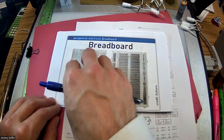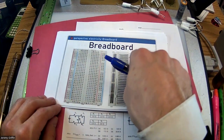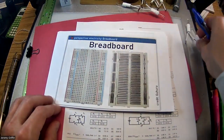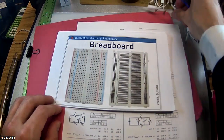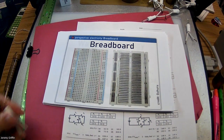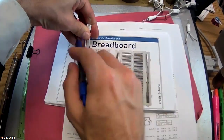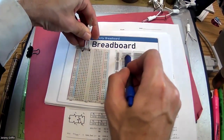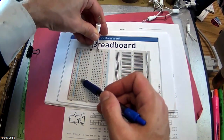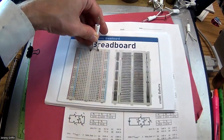So if you know what's going on in the back, just look at the front, because the front just looks like a bunch of holes. But if you know what's going on behind the scenes, you can know how to wire things up. What I would not want to do with a single resistor is plug it in something like here and here. That would be completely pointless because there would be a metal strip underneath it that has basically 0 resistance. So this would always be shorted out and it would never turn on. Now, if I bridge this gap like this, the electricity is forced to flow through that resistor.